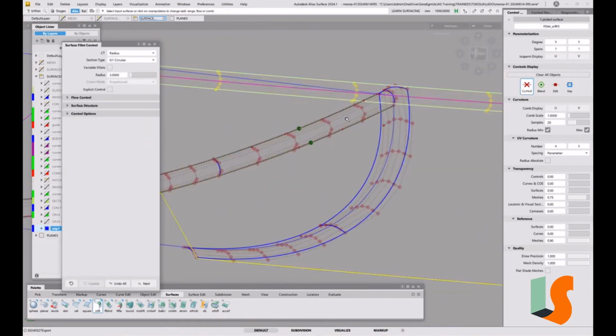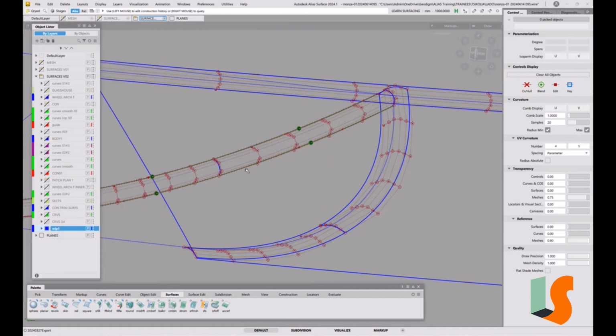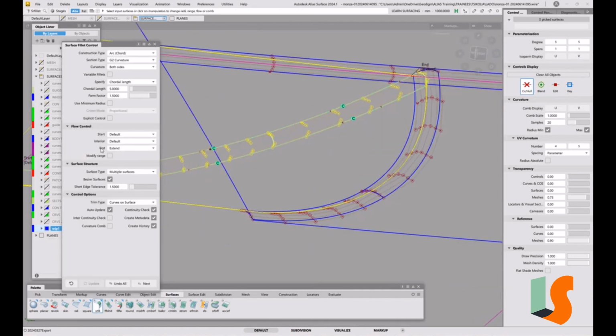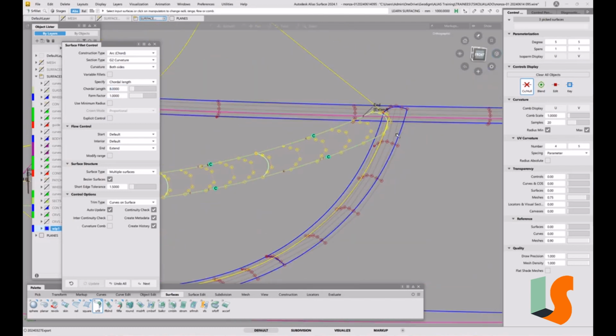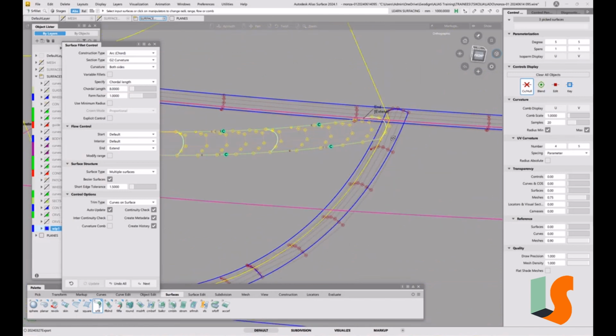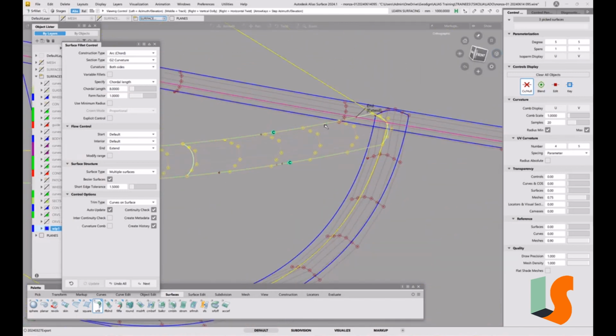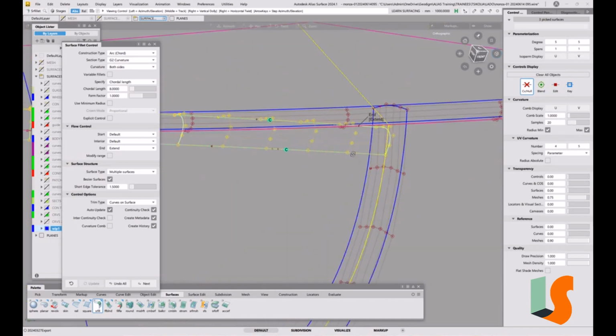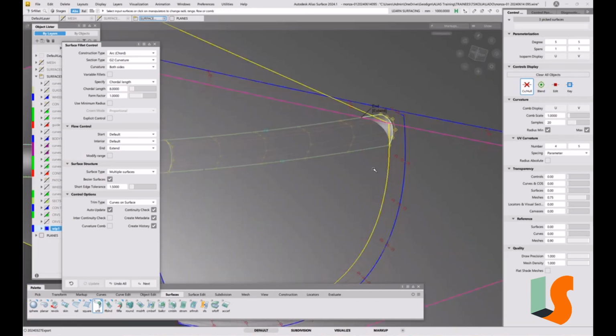I think I'll make that a little bit bigger. So query edit that. It's putting a form factor of 1.5 in for some reason. We'll make that bigger. 8 mil is one of my favorite numbers when it comes to fillets for some reason. It seems to give a nice result sometimes. So we go with that.